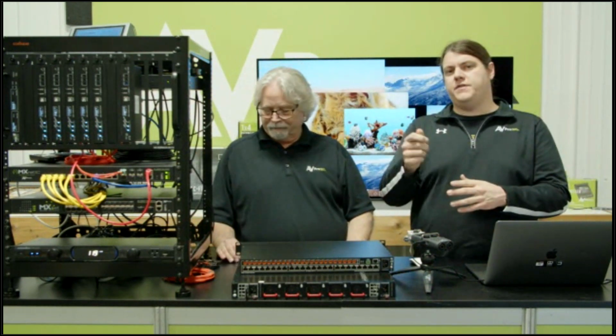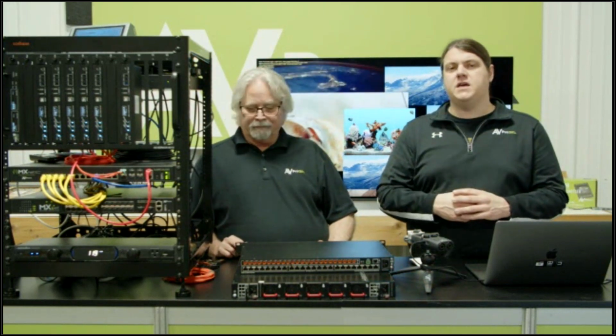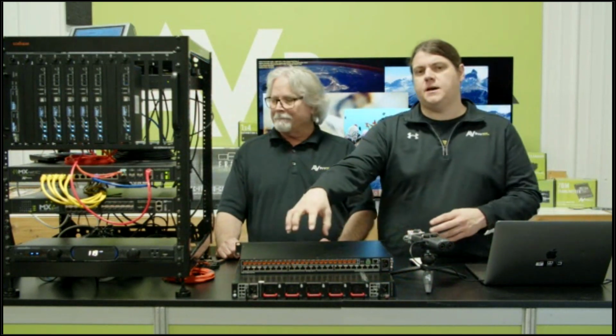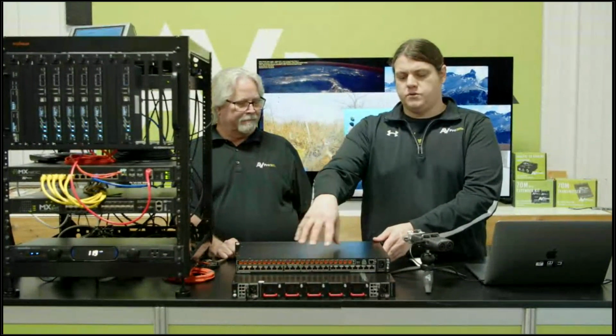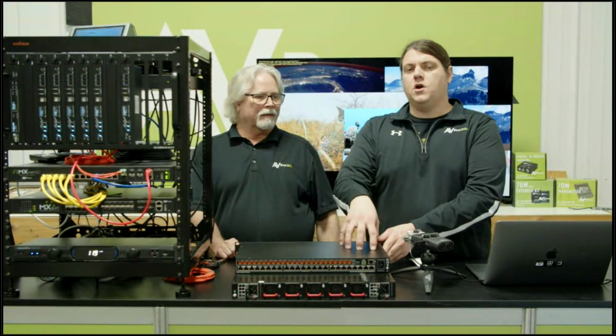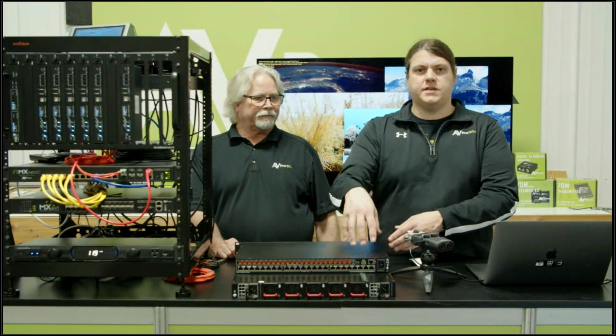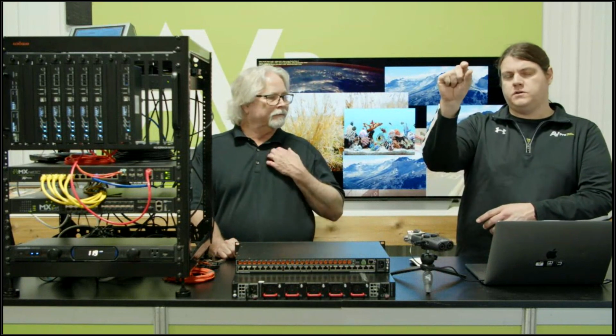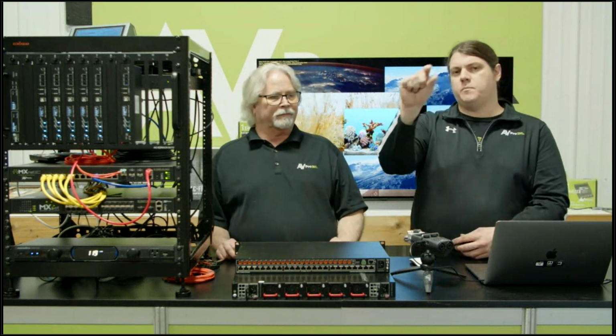So not an 18.2 to the 12 volt. No, definitely, exactly, Ryan. You don't put it to the barrel connection. You would use it to the PoE connection, because this is a PoE provider. So it's providing the exact amount of power for PoE. It's actually not providing a 12 volt signal that you would find from your barrel connection.